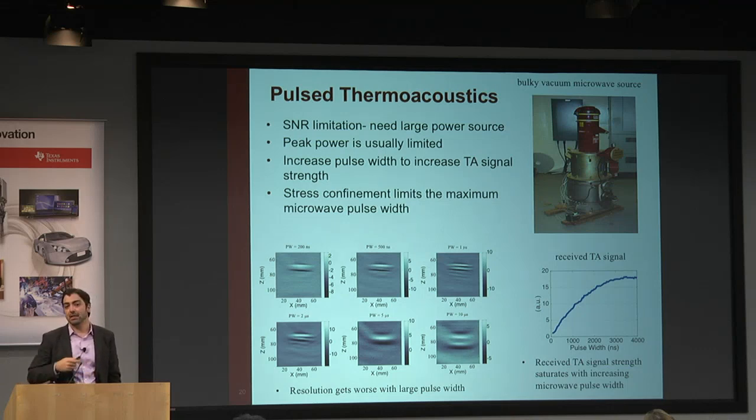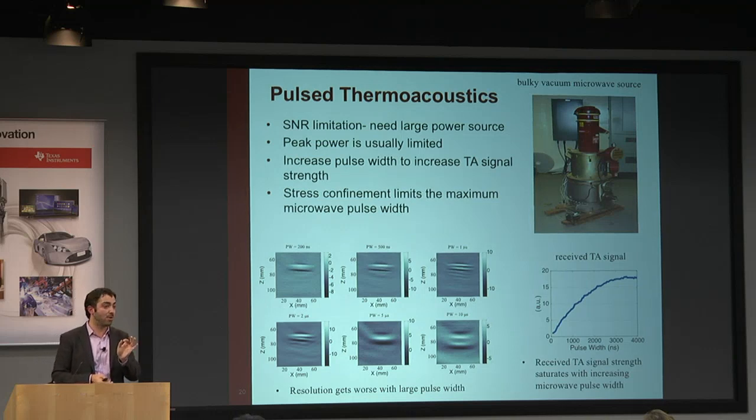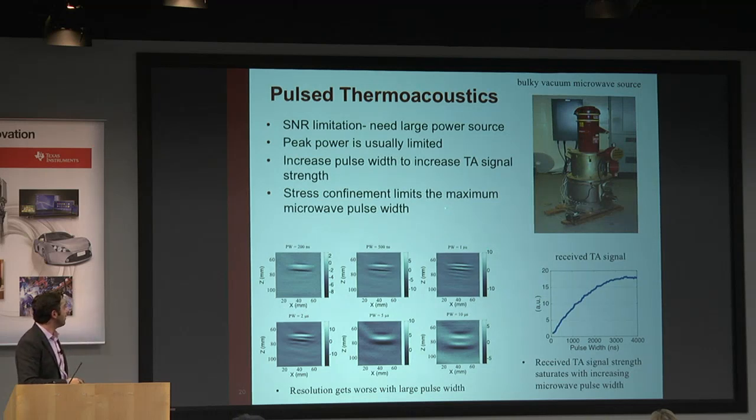In photoacoustics, you use the equivalent laser that has tens of millijoules, 10 to 20 millijoules of energy per pulse. So again, hundreds of kilowatts. If this pulse is a nanosecond and it has 20 millijoules, we're talking about a very large power per pulse. And so we are limited in terms of resolution, or in terms of signal-to-noise ratio. Now, you might ask, well, if you want this to be scalable, you really need to do it in semiconductors. You need to do it in III-Vs, gallium nitride, eventually maybe silicon. Doesn't work if you have vacuum sources. It kind of defeats the purpose.